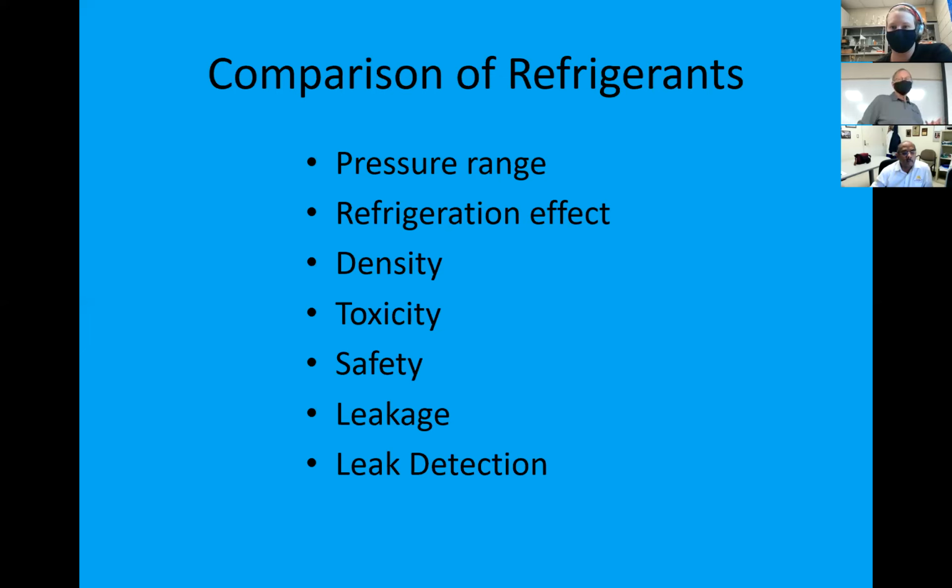Toxicity, something to keep in mind. Of these, the one that's acutely toxic of that list, the more common ones, is ammonia. You can make the argument that the freons are toxic, but they would be more long-term toxicity, screwing up the atmosphere and so forth. So that gets into safety.